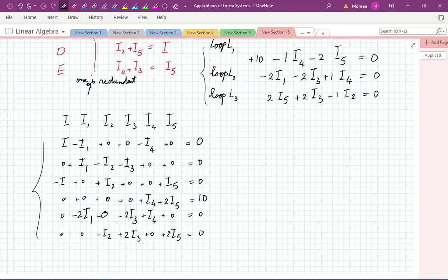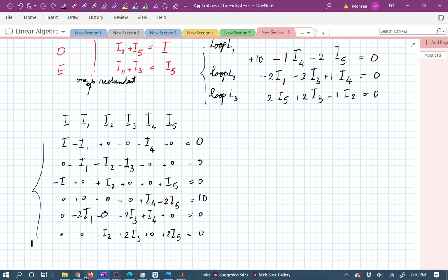So what do we want to get out of it? Well, whatever the problem is asking us, we essentially want to figure out our currents. Once we have the currents, we can calculate a variety of potential drops. That's multiplying the current with the resistance, and you figure out the voltage by Ohm's law. Now this is a 6 by 6 system. It's going to take a while if you want to do it by hand, so we resort to our software. Let's hope that we enter it correctly.